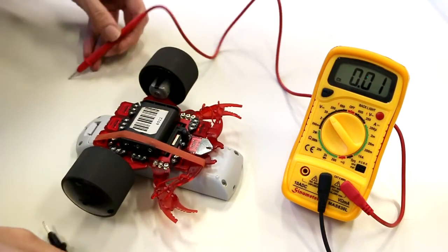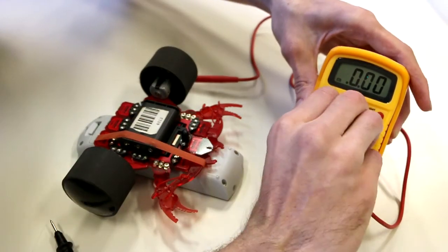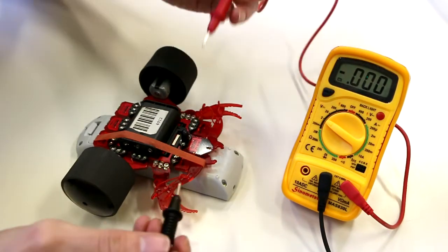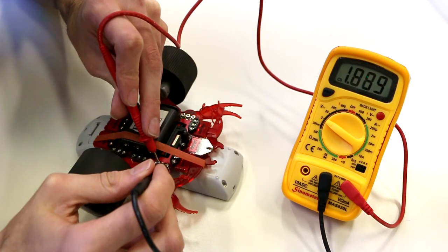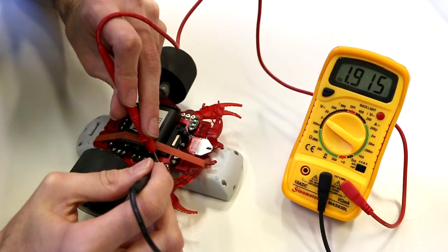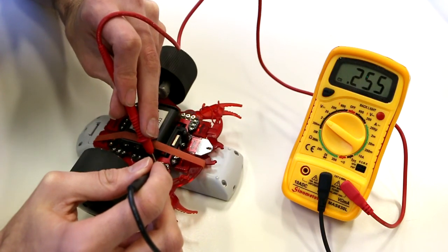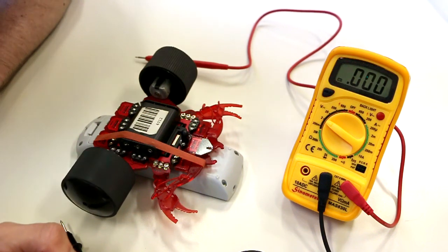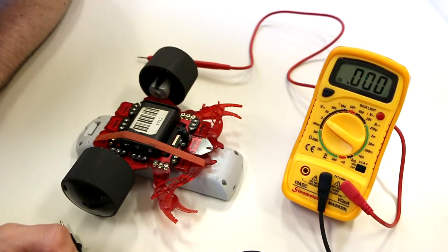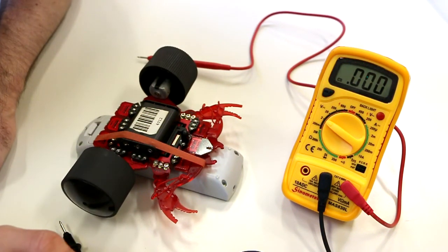And just to demonstrate, just for science, we'll swap it down to the 2 and take one last quick reading. There we go, that looks a bit nicer, 1.915, which of course we can just round up to 1.92. So there you have it, that's how you take a voltage reading of the LED module inside the AI2 robot.